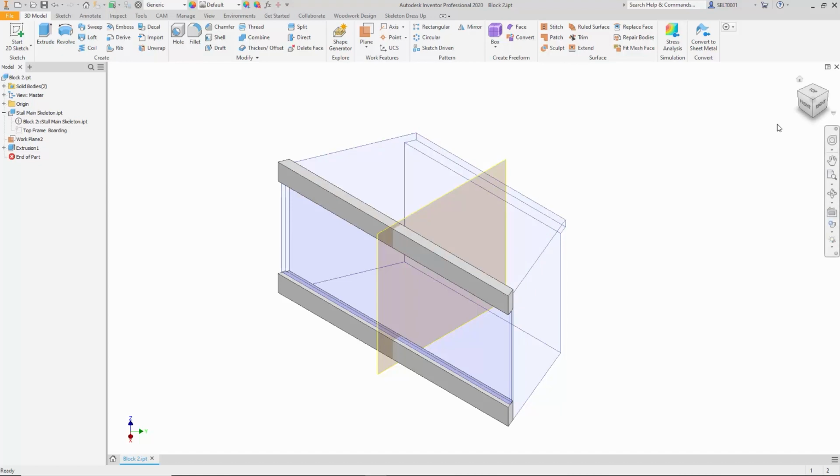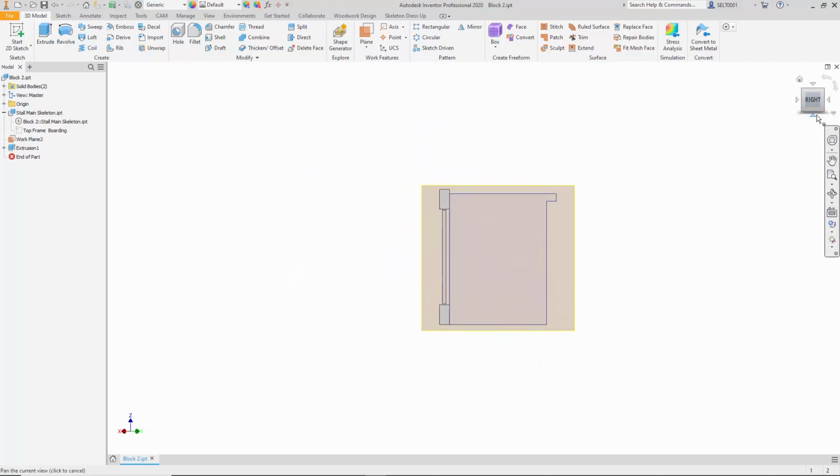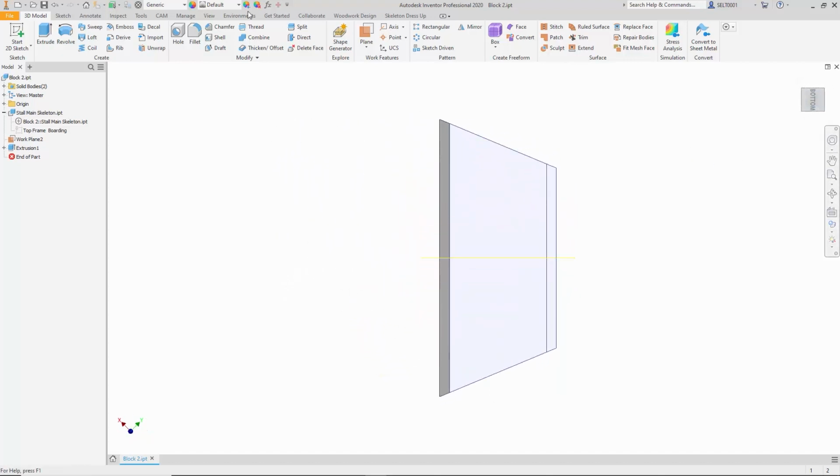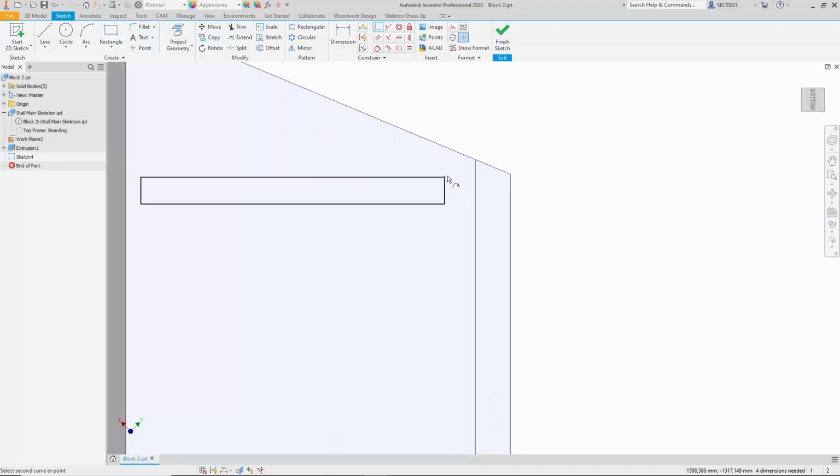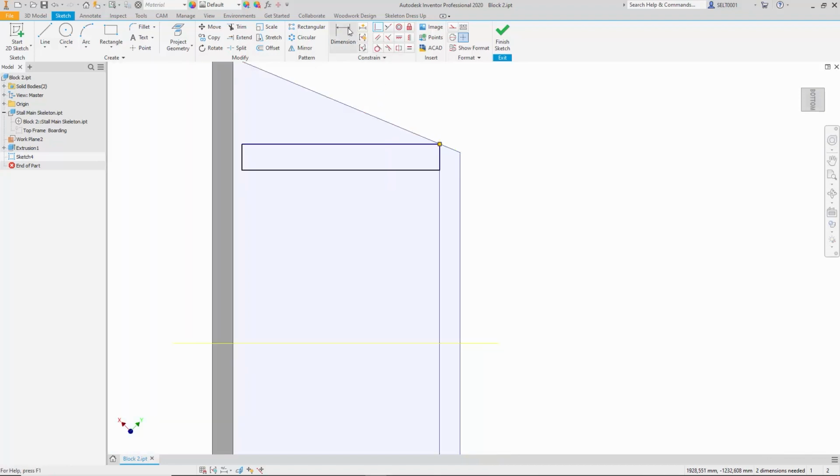Next, two bodies are stretched from one plane to another plane. A new body is generated. Add additional legs that will indicate the place for the cabinet in the structure. To do this, you need to stand on the bottom of the sketch and indicate which angle coincides with another angle. Profile width 20 mm.